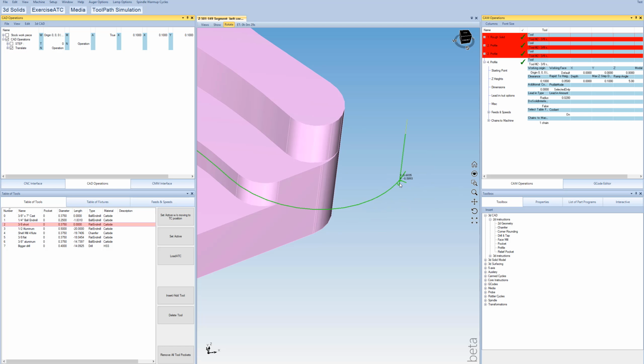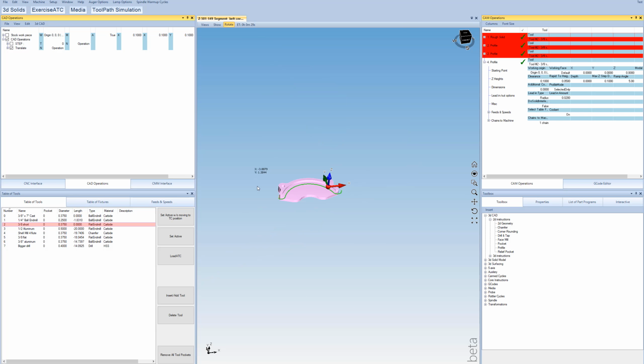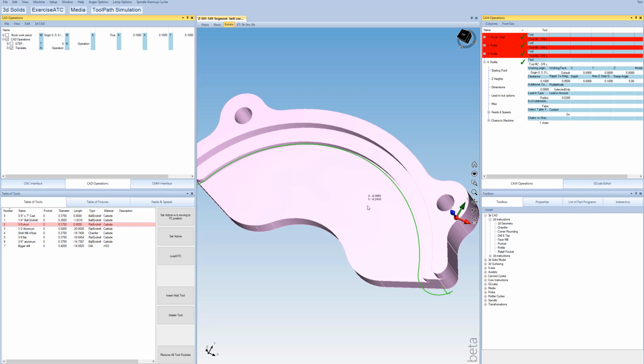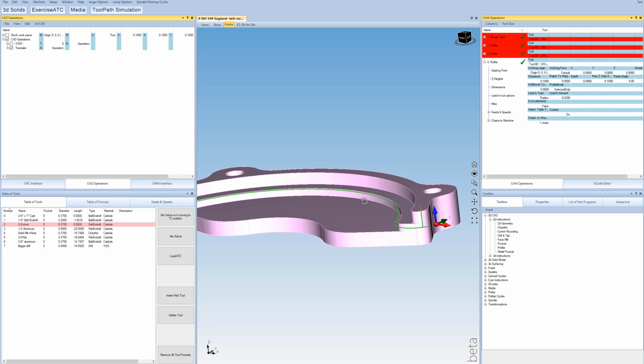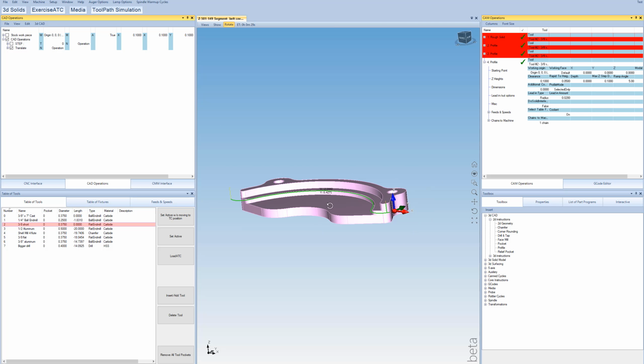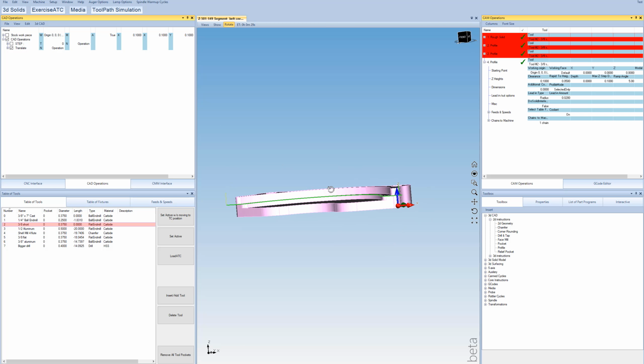So that's going to start over here, and just go around and cut that whole thing out in one cut. And again, just like I explained on the full perimeter, we could do this in 2 cuts if we wanted a finished pass. Probably not required because this is really going to be cut down after our rough solid routine. And I think that's pretty much it.